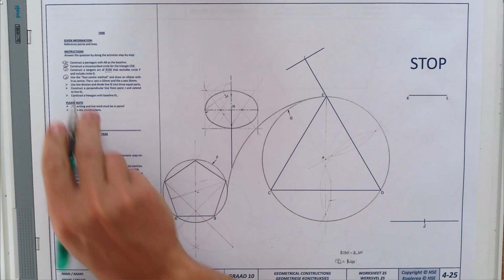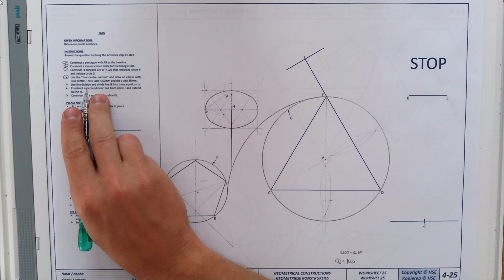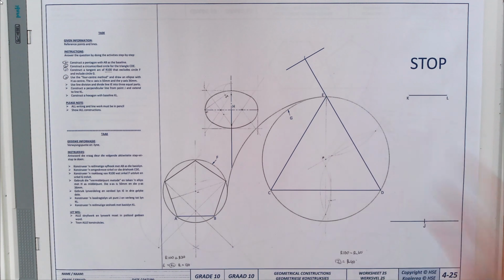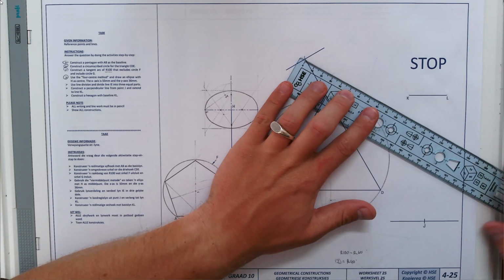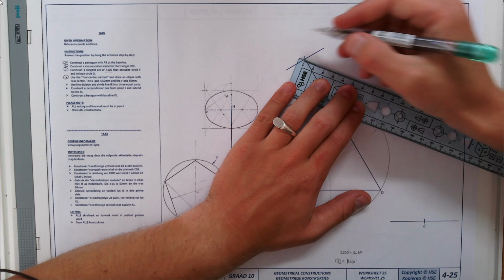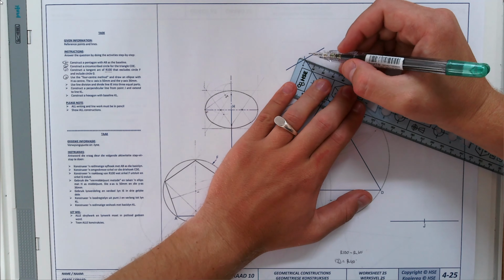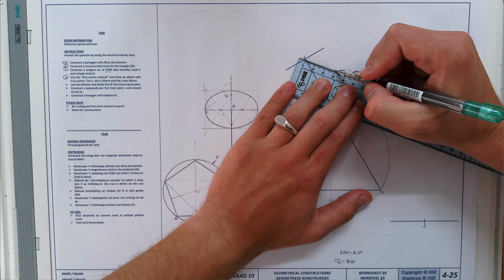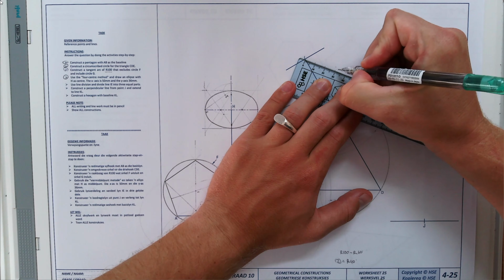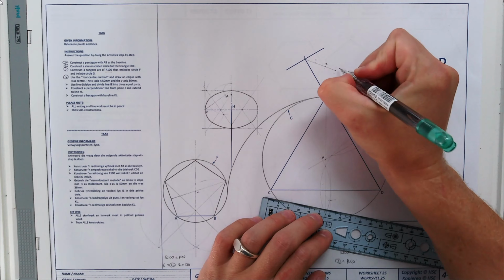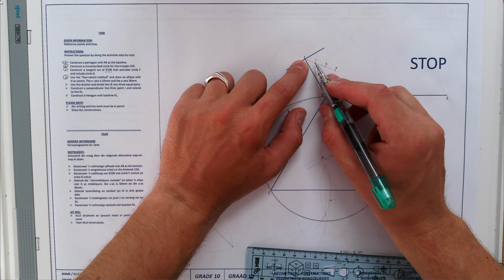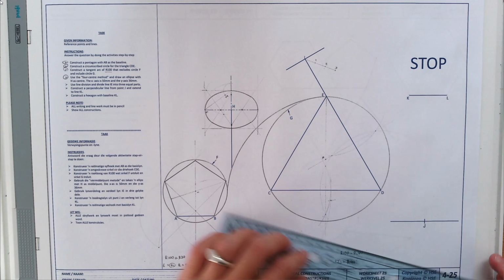There's our ellipse done. Now, use a line division and divide line IE into 3 equal parts. There's line IE. We are going to divide this line into 3 equal parts. So I'm going to draw a line at any degree from I, and I'm going to draw a line with a length of 30 millimeters. For each 10 millimeters, I'm going to make a mark. 1, 2, 3. So this line is divided into 3 equal parts now. For each 10 millimeters, I've got one division.